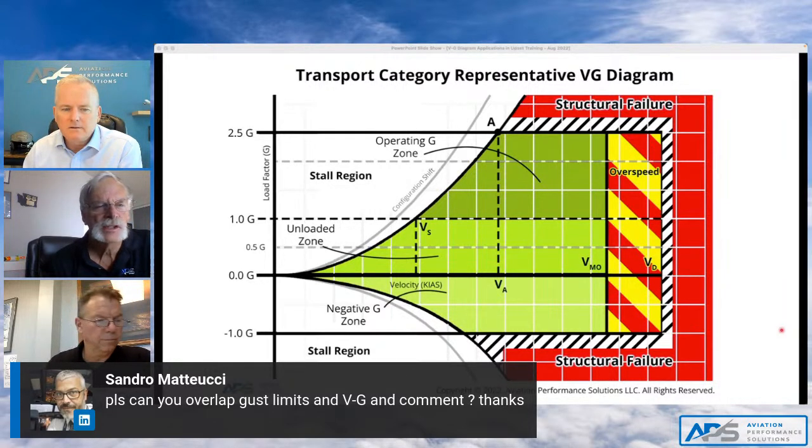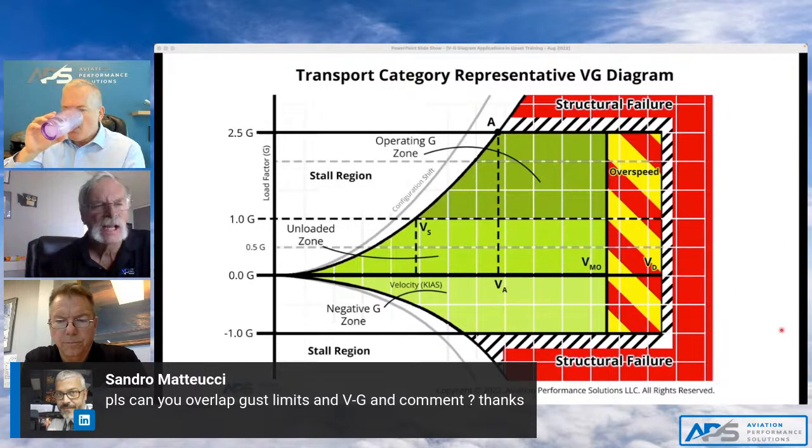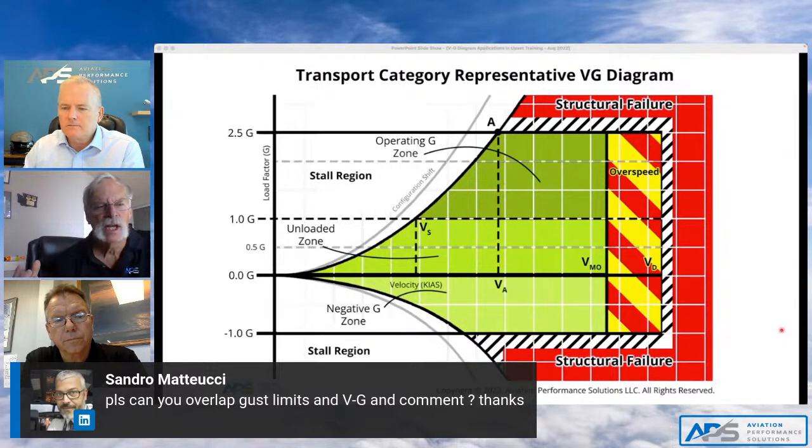The gust limitations for a commercial transport category airplane are basically immaterial compared to a smaller airplane, just because of the total energy involved. The gusting factors just don't move you around the VG diagram like they would for a very small airplane. So basically consider the limits that you're seeing right now applicable to gusty winds or not.